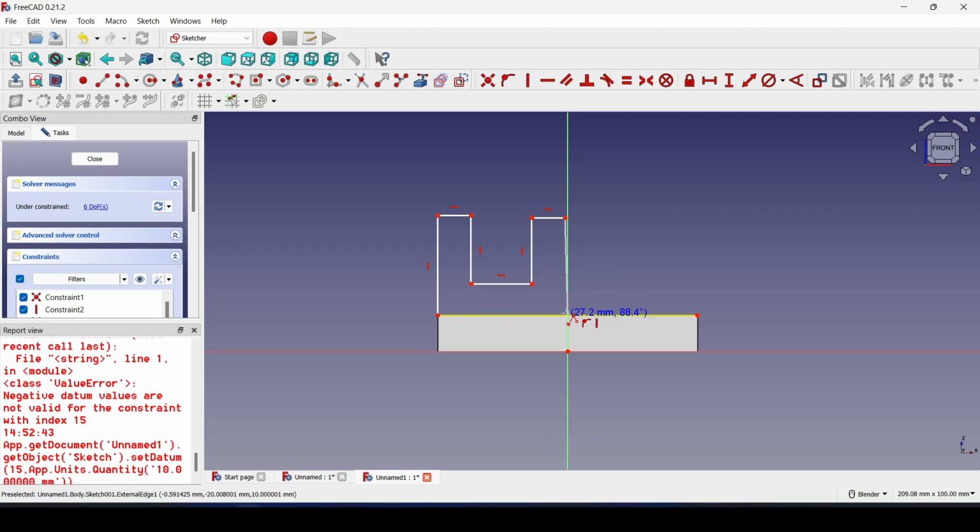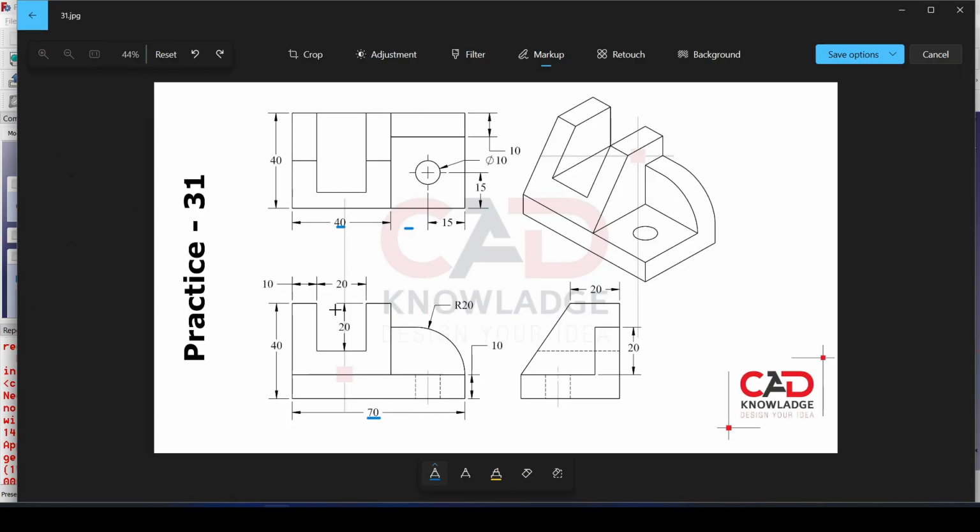And I'll bring it all the way down. And again, I will create the vertical constraint, the little line you see there, as well as the point on object constraint. Okay, you can right click to get out of that line selection tool on the polyline. Right click again. So now we'll want to go ahead and define some dimensions on these lines that we created.